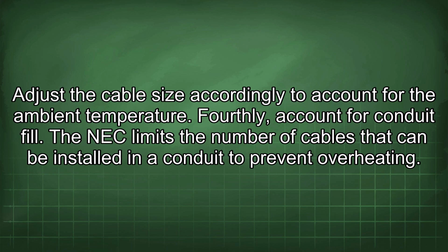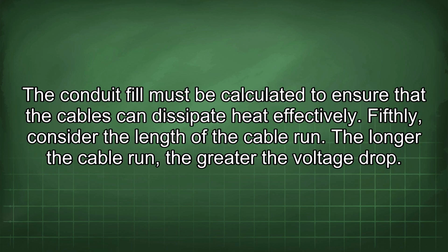Fourthly, account for conduit fill. The NEC limits the number of cables that can be installed in a conduit to prevent overheating. The conduit fill must be calculated to ensure that the cables can dissipate heat effectively.